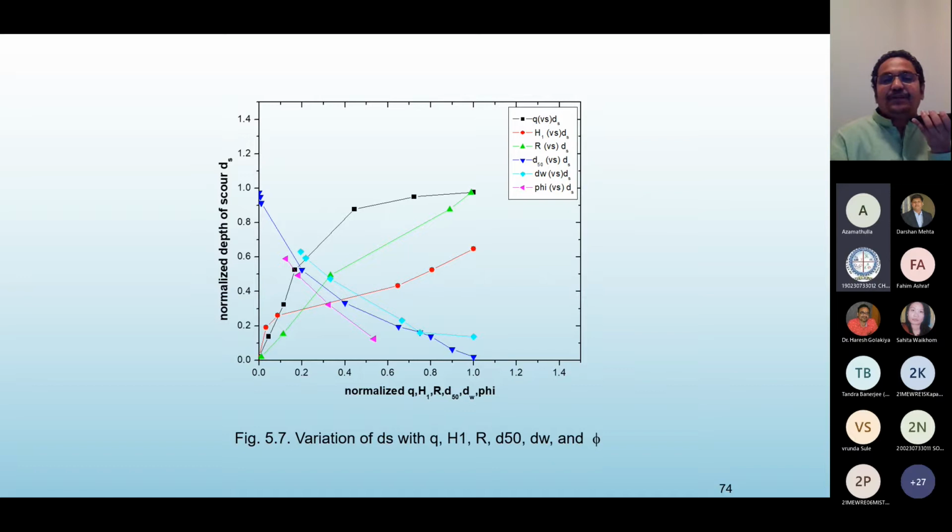So in the case of bed material, that is why I said in the scope of the study that rock mass rating and rock quality designation are very important. You can see the big boulders in the prototype, and also the depth of the water level here. So that is why the plunge pool is important. Okay, next please.